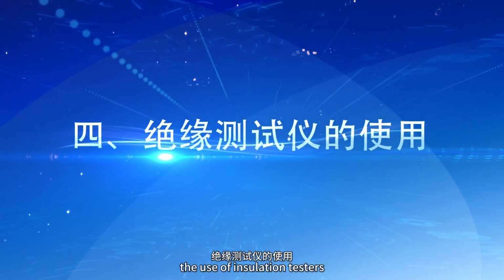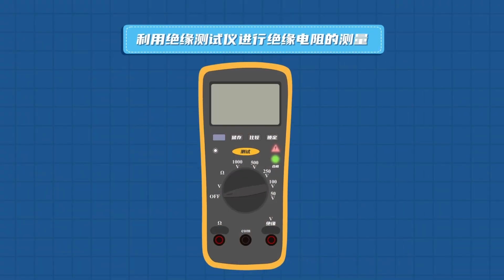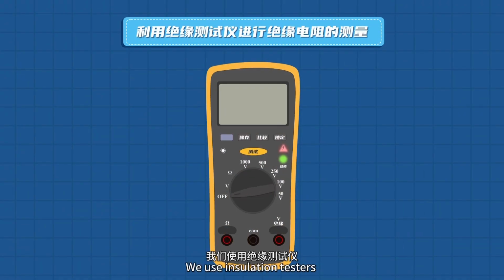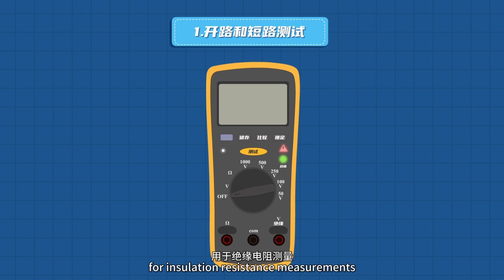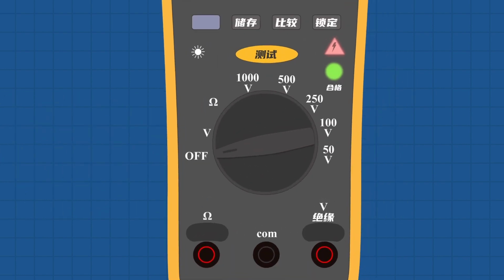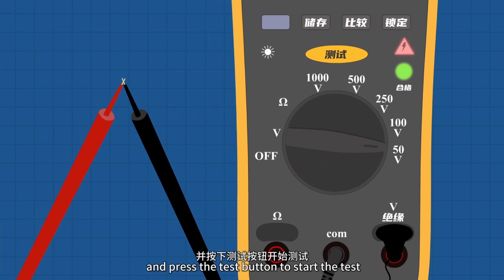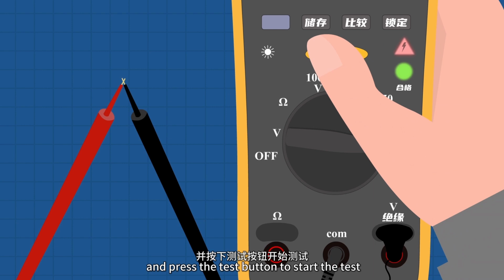Fourth, the use of insulation testers. We learn about insulation resistance measurements in the form of an animation. We use insulation testers for insulation resistance measurements. Put on protective gear and plug the test probe into V and COM, common input terminals. Firstly, zero the test. Turn the rotary switch to 50 volts. Make a short circuit on the two probes and press the test button to start the test.